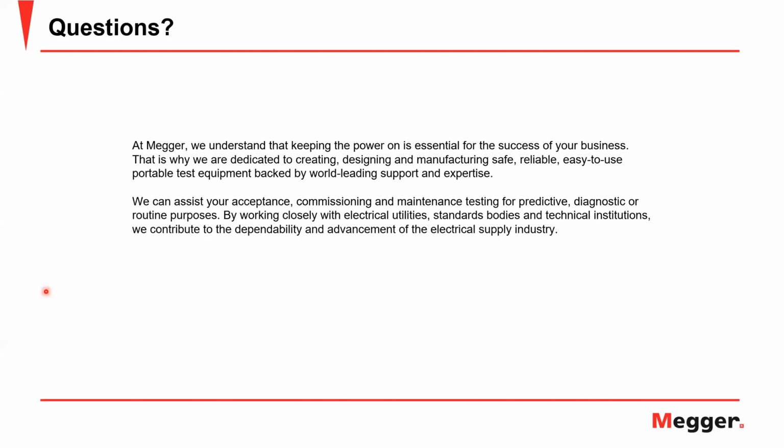Our first one I'm going to send over to Mohit. Is it better to make the CB trip before the fuse due to the time spent replacing the fuse? It could be. It all depends on the utility practices, as Mike was explaining in his presentation. Various utilities adopt the philosophy of a fuse saving scheme, whereas some adopt a fuse blowing scheme. In the fuse blowing scheme, all the fuses are gone, and then you have to send manpower out in the field to replace them. So there is this manpower cost and the outage cost.